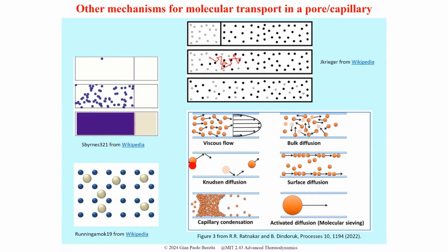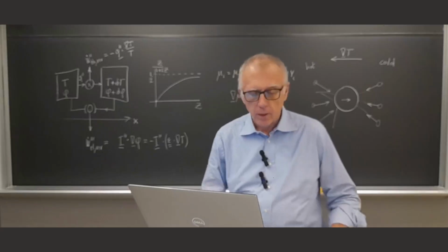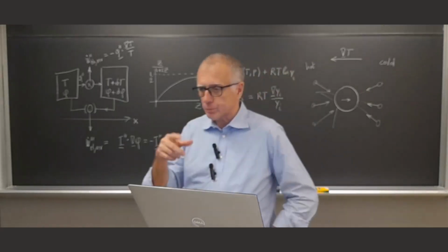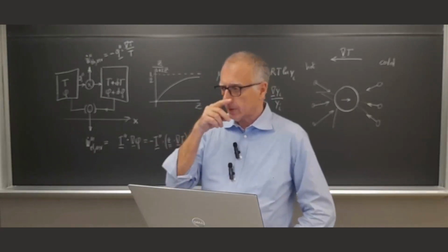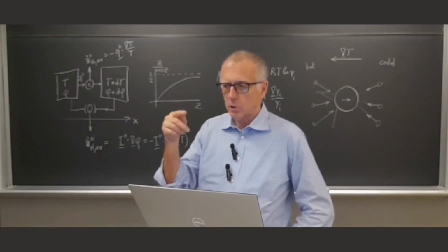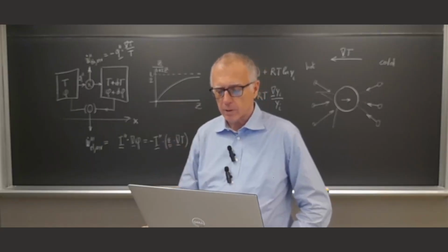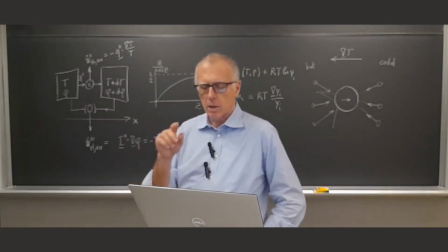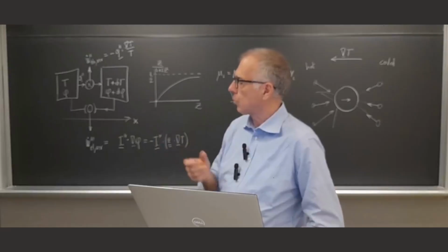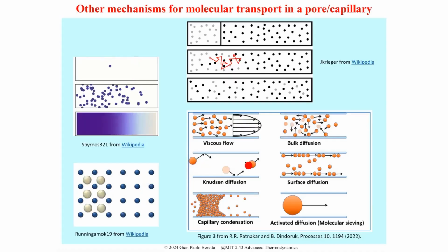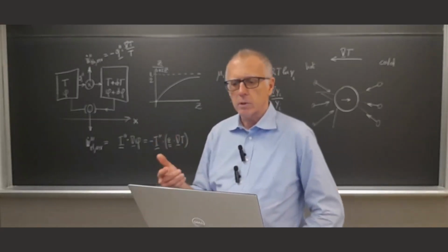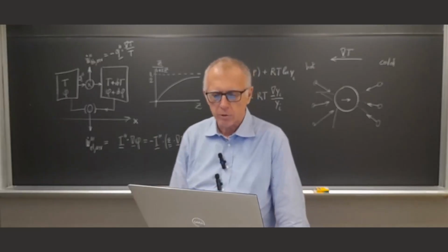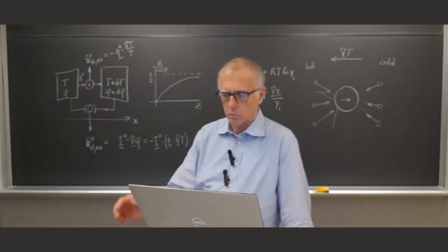So if the Knudsen number is very small, then your particles, let's say that if they make at least 100 collisions before traveling a distance of the order of magnitude of your device, which could be the diameter of your pipe, then we are safe, and you can make the continuum assumption that we have made in what we've done.